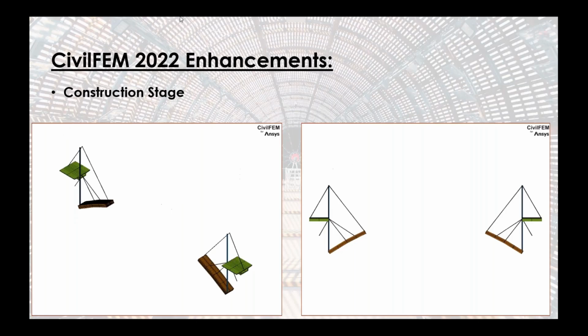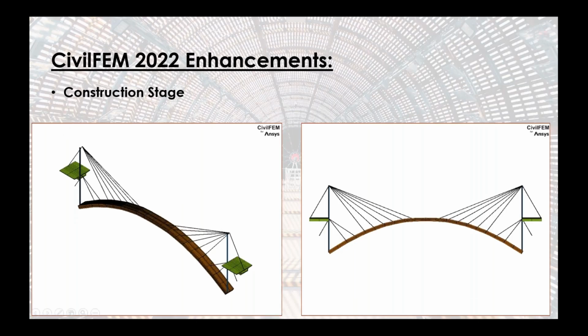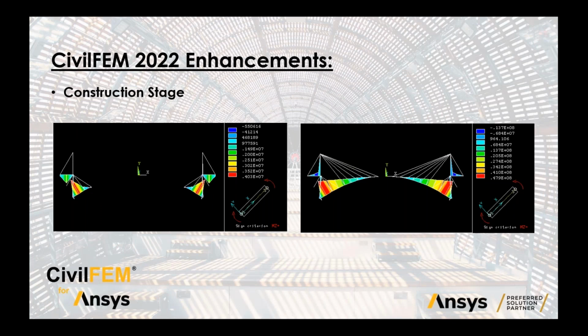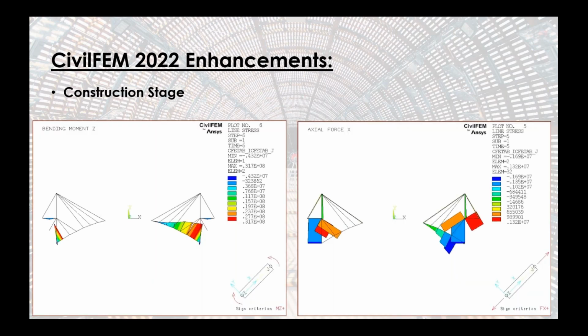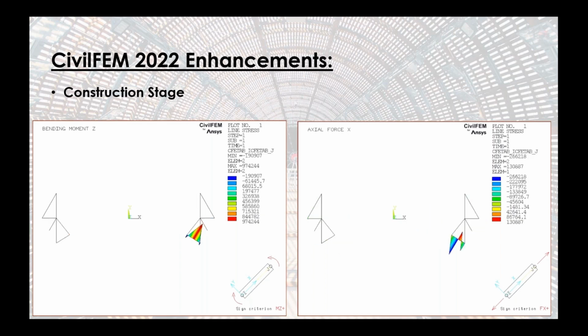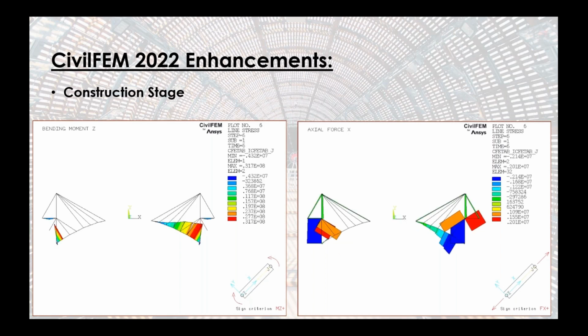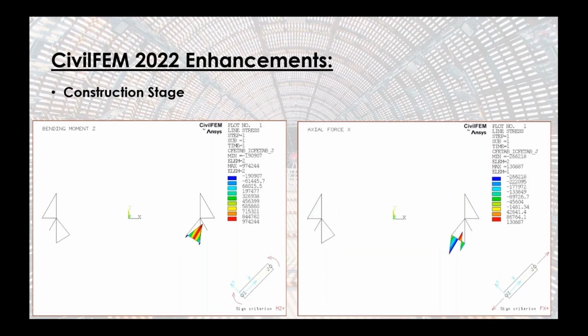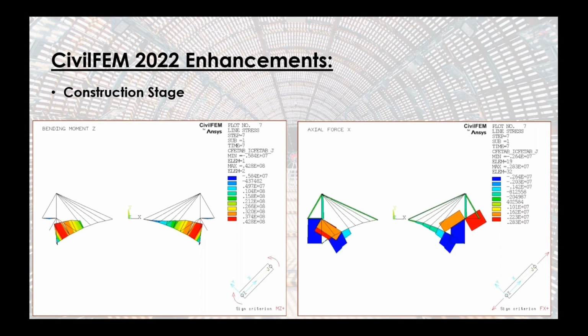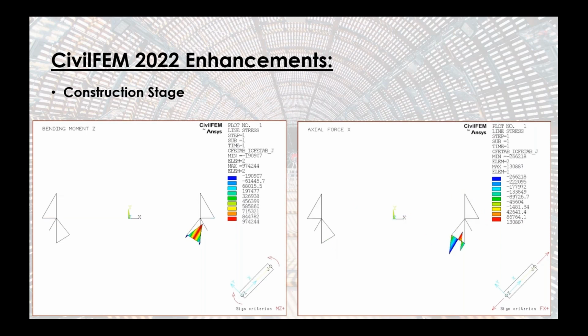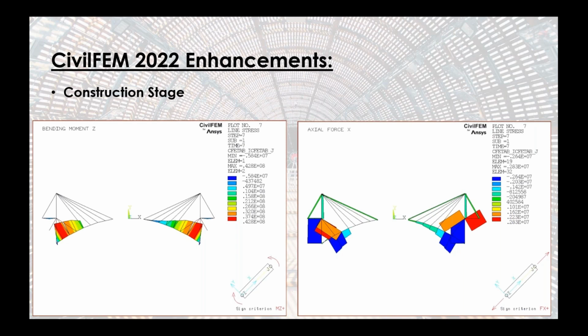We can perform a construction process and also design all this construction process. Here you can see some plots of bending moments due to this construction process. Also, we created an envelope of the reinforcement amount that are needed during all the construction process, and also once the bridge is constructed, the overload combinations, and we create a final envelope of the reinforcement amounts.